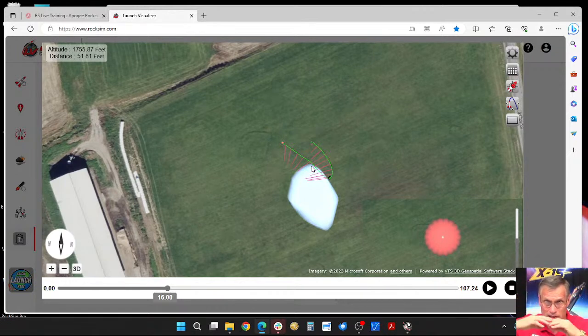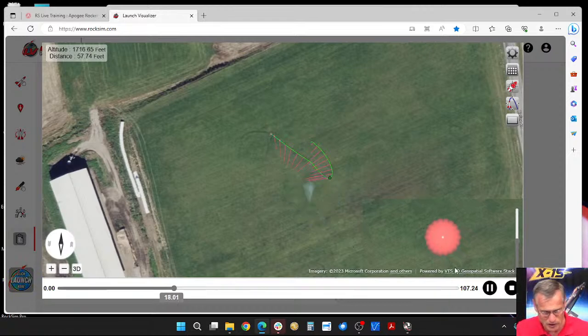Since we made it exactly at 6,000 feet, it's going this way, and at ground level is this way, so the inflection point is going to be exactly right in the middle at 3,000 feet. Since we didn't get to 3,000 feet or above with this rocket, it's only seeing wind blowing towards the north. And so if we continue the flight of the rocket, it's drifting that way.